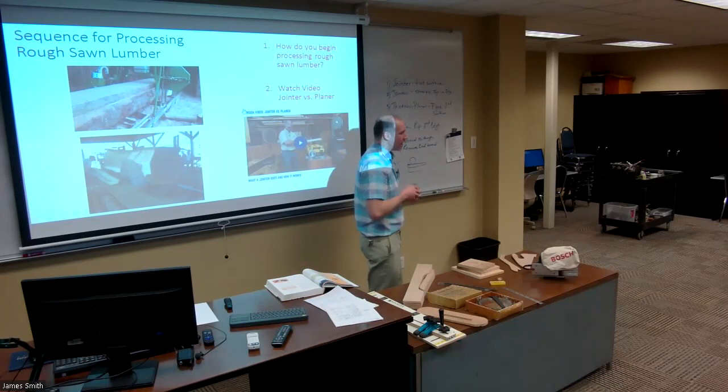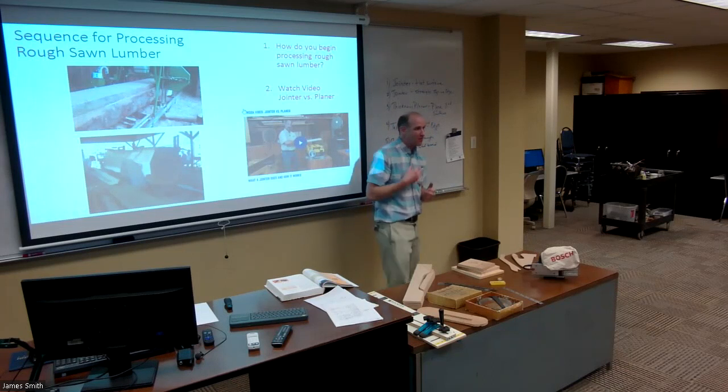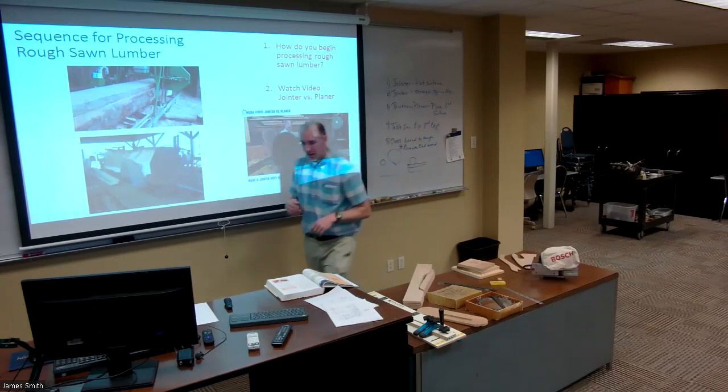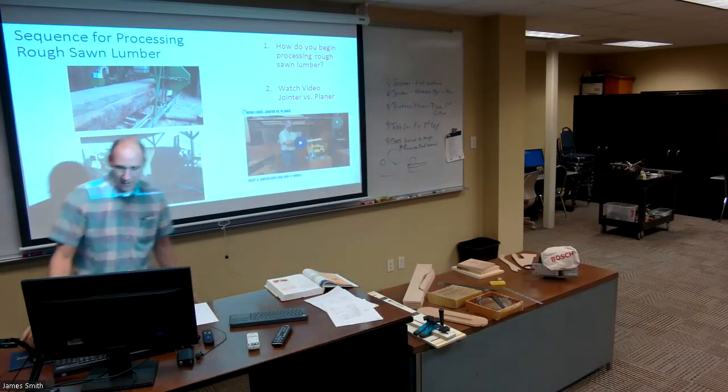How do we get around that? Well, you can use a double-sided planer and cut off both the top and bottom at the same time, if that helps. And that's probably the biggest reason why I buy my lumber already skin planed with a straight edge, so that the distributor can worry about it. Because that's kind of heavy, and you've got to have a lot of skill to do that.